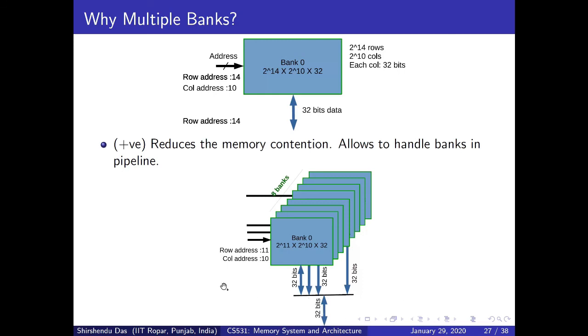And this is very interesting. Why is it very interesting? Because if you remember what I said in the previous slide, about how a read write operation is performed in a DRAM bank, there may be many steps. If this information is not already there in the row buffer, then we have to go for an activation command. That means first of all we have to activate the particular row, and then all this information will be available in the row buffer.